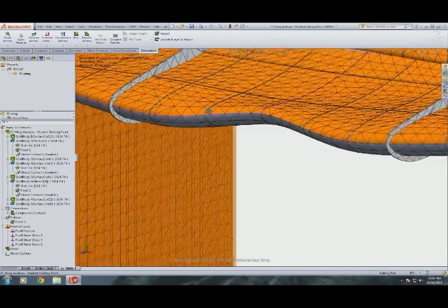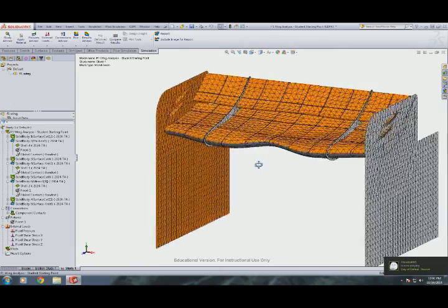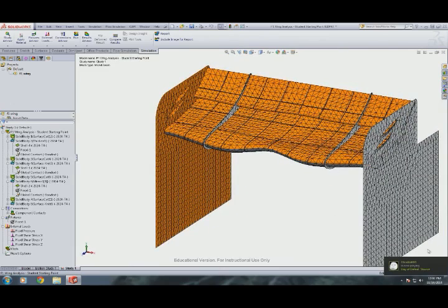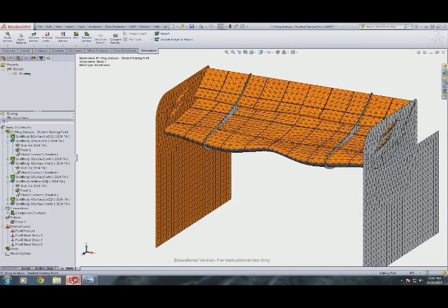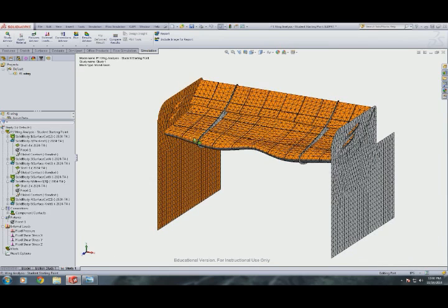So if we ran it right now, we would most likely see a photo that looks like, if I can pull up the reference picture that I made, there's the correct one. A photo that will look like this, where the ribs stick through the surface. When you actually bond these ribs to the surface of the skin, interestingly enough, SOLIDWORKS knows to bond to these edges where you get a 90-degree butt joint.